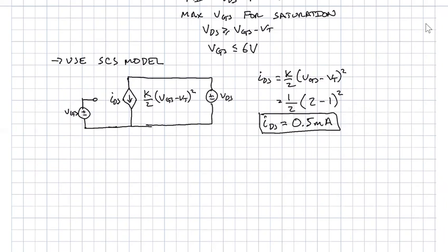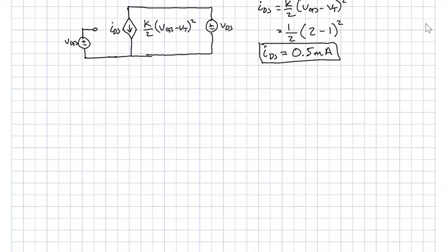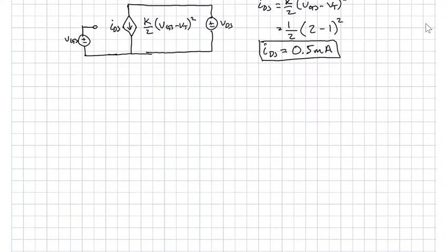There are no discontinuities in this piecewise linear. It'll model the IDS versus VDS current over the full range of operation. But again, it's not something that we necessarily always have to deal with, because we typically want to stay in triode or saturation. So I think this is section 7.8 in the book.